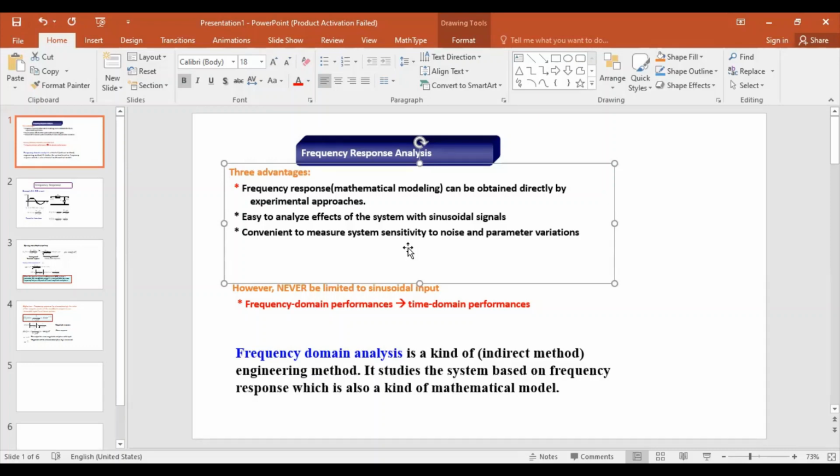Fine. So what I mean to say is that by applying a high frequency, we are experimenting with a situation on the RLC circuit where our high frequency input signal equivalently represents a noise, because noise is something like a very high frequency signal. But a practical noise will comprise signals of very different frequencies, or high frequency signals which are different from each other.